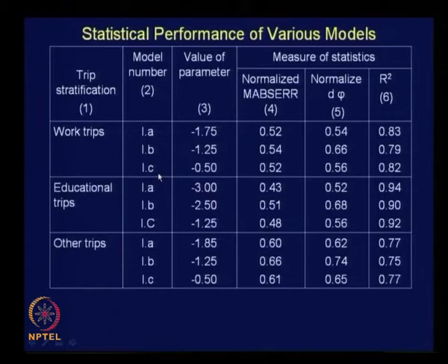In addition, we wanted to have a singly constrained model to be calibrated by the Bpr method. That type 2 is not listed here; the results pertain to type 1, all doubly constrained models, okay. And you can see the value of the parameter here. Suppose in the first case it is alpha, in the second and third case it is beta, e power beta something we had, you may recollect the model, right.